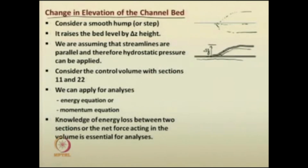We are suggesting a smooth hump here. The rise in the bed level is smooth. Streamlines are not bifurcated, or disjointed. So, streamlines are still parallel in that particular flow. Thereby, we can use hydrostatic pressure conditions to evaluate the pressure in the liquid.